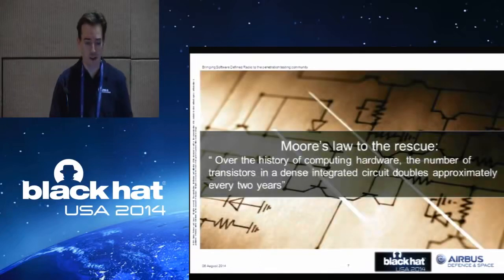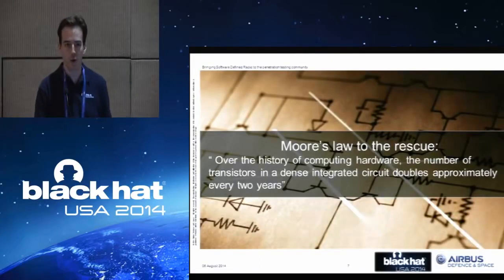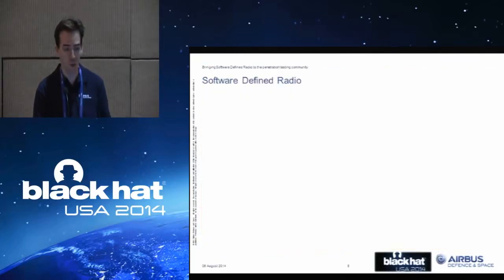Fortunately, computers are getting more and more efficient, so we can move what has been done in hardware to your CPU instead. And that's why we are dealing with software-defined radio. It is basically a configurable local oscillator. No hardwired processing is done. You just have a local oscillator, preamplifiers, filters, and an ADC, an analog-to-digital converter. It will just stream raw digital samples to your computer, and then your CPU will do the rest.